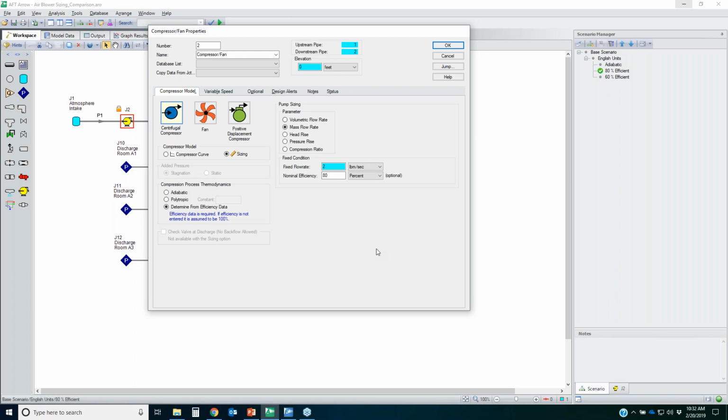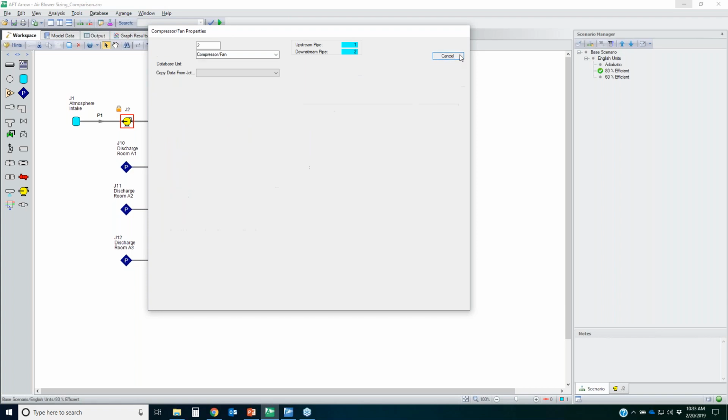So that's why if you have standard or normal and then the volumetric quantity, it's considered a mass flow rate, not a volumetric flow rate. So if you want to do standard cubic feet per minute, what you would need to use is mass flow rate as your flow parameter. And then in your drop-down menu, you would change your units to SCFM, or perhaps you might be using normal cubic meters per hour, for example.